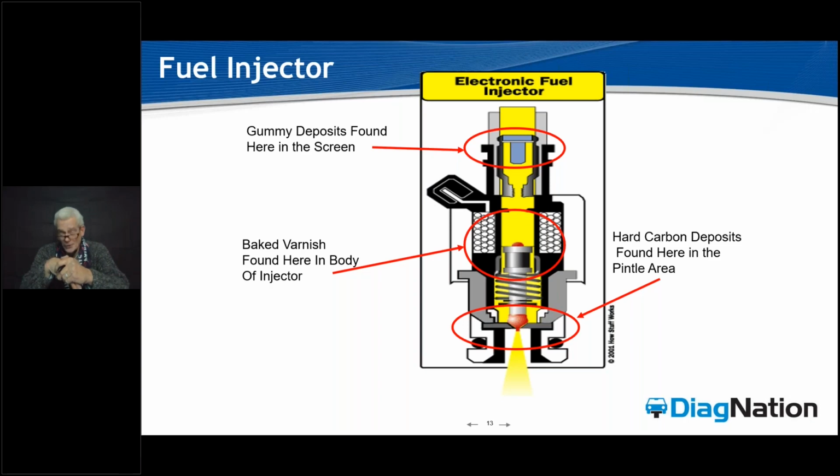I've also had others, like a Chevy Cruze we had last week, that had a ghost lean code that went through thousands of dollars worth of work at 2 dealerships and an independent shop. And it turns out all 6 injectors were badly fouled like this here in the top, and a fresh set of injectors straightened that car right out. And I'm talking, this is after they threw PCMs and programmings and all the bulletin stuff at it. These guys went nuts figuring this car out, and it was diminished flow through the injectors. So this is where we're going to get the gummy deposit.